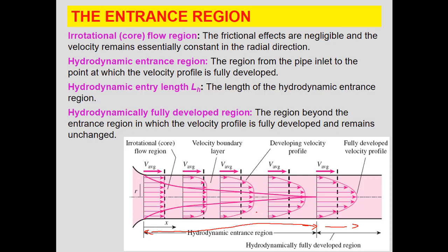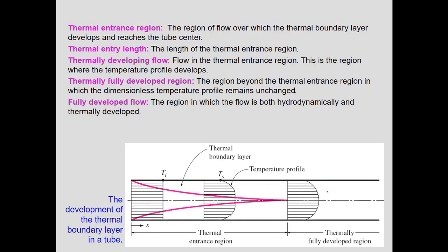Because its characteristics, especially this one, will be effective on the required energy and to design a pump, to select a pump actually, and also it is effective on the following velocity. And from this point, the velocity will be constant, and we can just use the average to have the velocity. And this L is not always small. Sometimes we can have just an imaginary L to have this fully developed velocity profile. Okay, so this is for the entrance region of the flow inside the pipe.